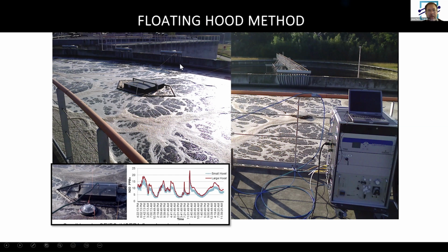But laterally, there could also be differences due to different mixing conditions. Normally, if it's a narrow channel and it's well mixed, there shouldn't be any significant differences. It's when the channel starts to get wider that the possibility for different local mixing conditions can be greater. But that's why we can be spot checking. We can move the hoods around to verify that.